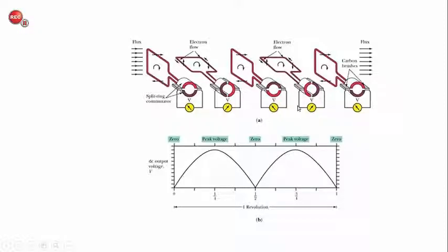And so the current comes out of the page, through the left brush, and from left to right through the voltmeter. That left to right direction of the electrons is the same whether the red commutator was on the right brush or the left. And that's the purpose of the commutator. It keeps the direction of electrons flowing in the same direction through the circuit, always through the voltmeter from left to right. And so the voltage induced across the voltmeter always has the same polarity, a positive polarity.